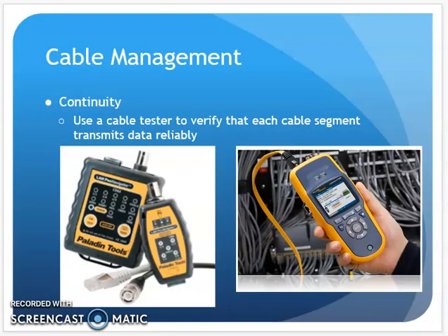After I install cabling, I should be putting a continuity tester on there to make sure at least I have a valid connection. These are the continuity testers that we actually have in our toolkits in our lab room. We also have these as well. This is going to give you a quick electrical test of, yep, there's a complete circuit here. This is going to give you a little bit more information about how long it is, and maybe whether it is able to carry the data that we want to carry. It's still a relatively basic test, but it's enough to let you know, yes, it's working, or no, I need to re-terminate it because there's a problem.